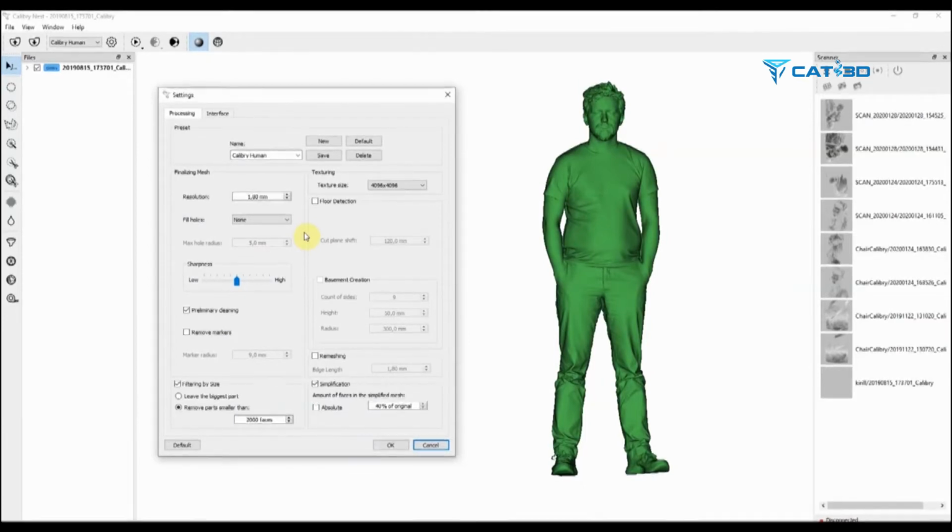But it's really helpful not only in this situation, but also in situations where your objects have some small holes that you want to keep. For example, you're scanning a metal part with a lot of really tiny holes in it, and if you choose to fill holes bigger than some radius, those holes should be bigger than that setting, otherwise they will be filled too.